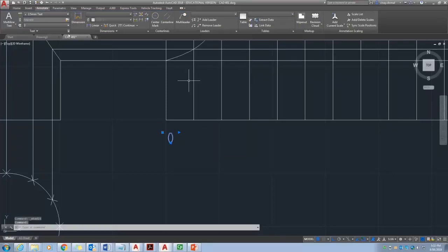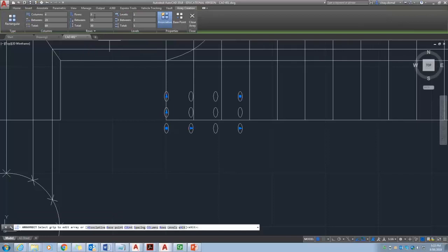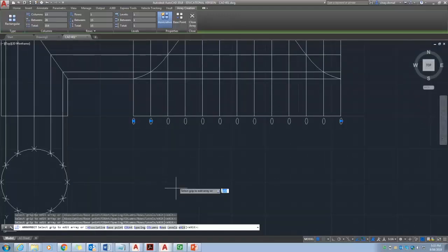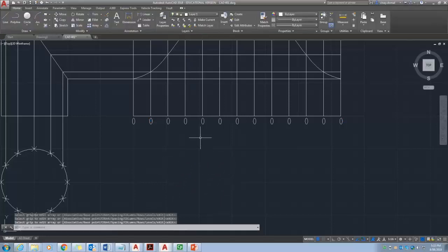So this one should go apply, move this one to, remove the ortho option, and I just want to center it with the line. Once you line it, it's easy. Now again apply rectangular array, 1 row, and this should be how many? 13 of them, and the overall length should be 314.15. So that will fit at the center now. Once it is centered, you can close the array and select again, explode that one, and keep editing the text.